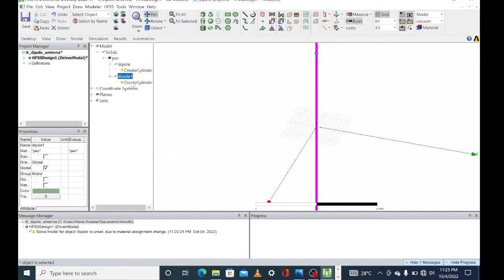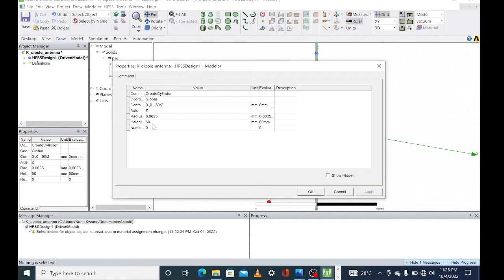What we will do is that we would change the height of this. We want the height of the second duplicated structure to be the height of our gap. So you get 0.125 for the gap, and we would make it divide the origin into 2. That is a midpoint. A midpoint should be between the gap.